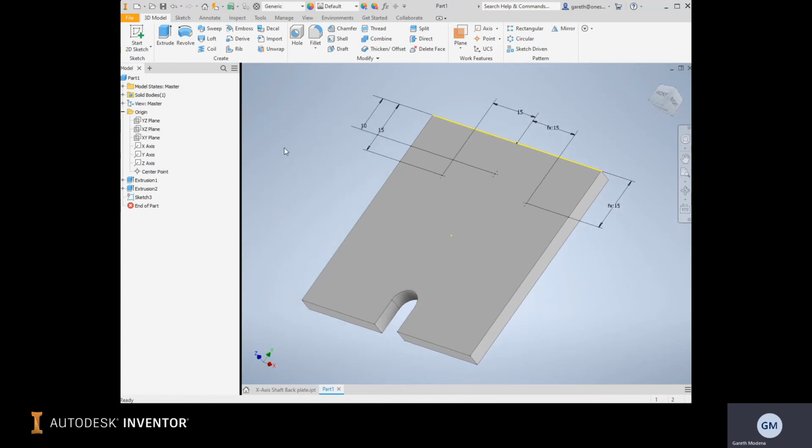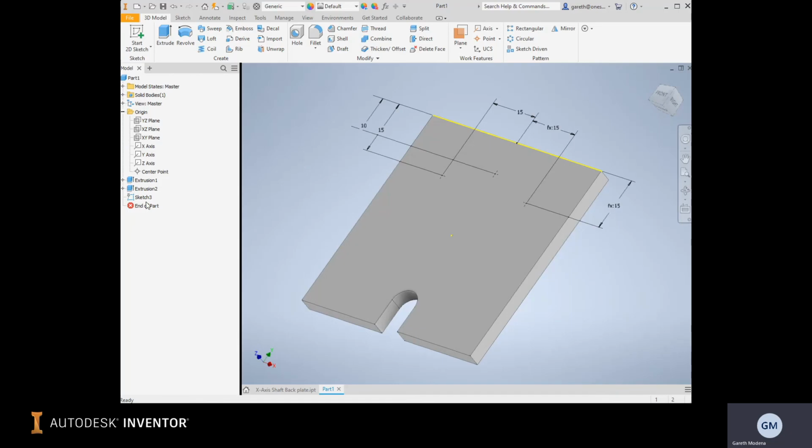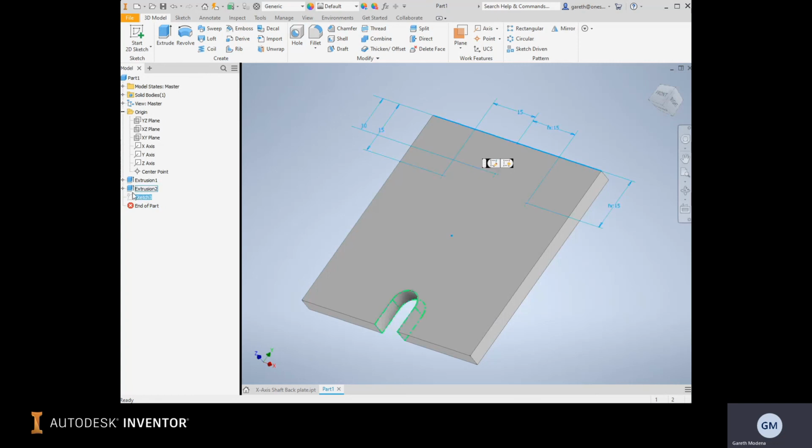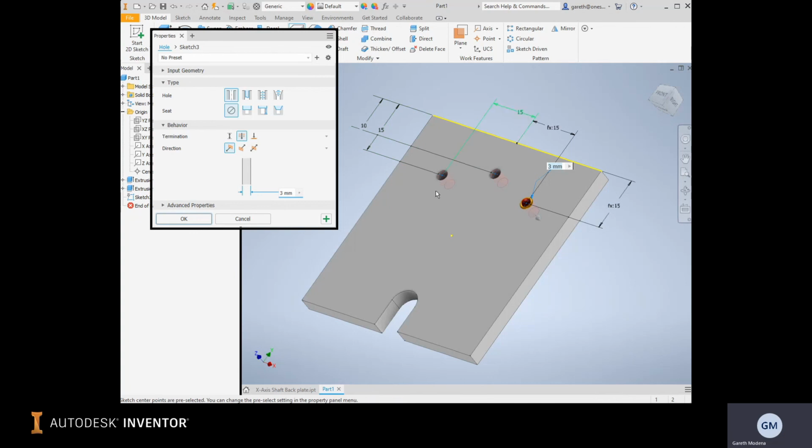Some of the other things about the sketch tool that I just want to cover briefly before we get into other segments around sketching. Sketches can be turned on and off by using the right-click visibility. It's still available, just not usable. So if you have an invisible sketch and you activate the hole tool, it then wants you to place individual holes. But if you've got a sketch visible with points in it, in this example, and you activate the hole tool, it auto selects the points that come in the actual sketch. So it makes it useful to lay out holes or